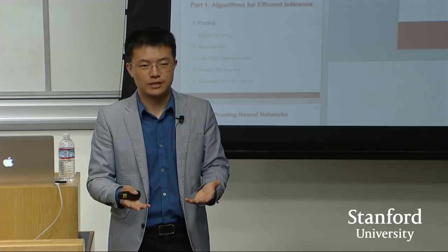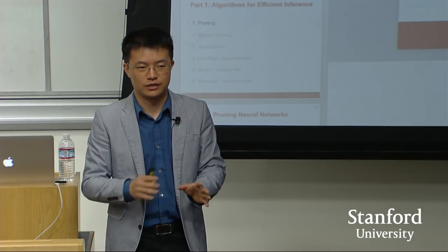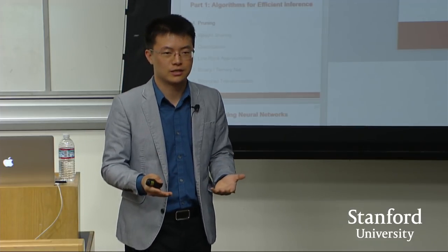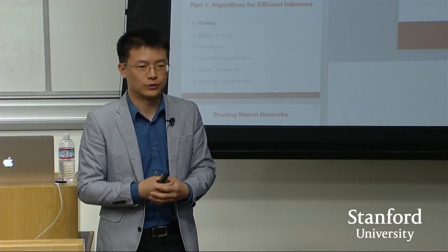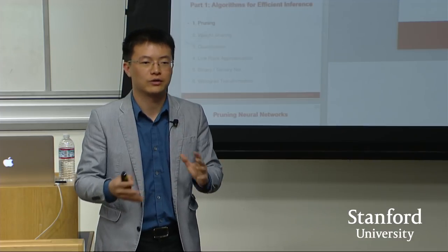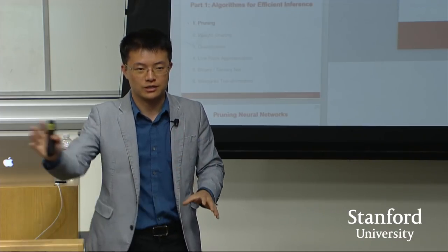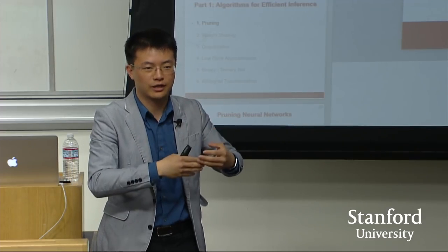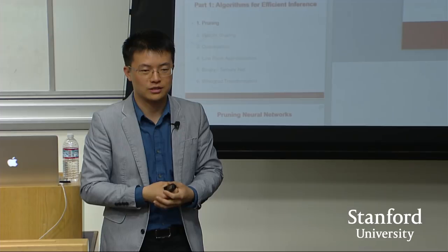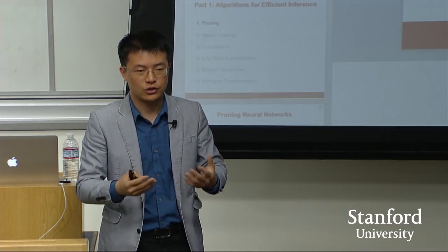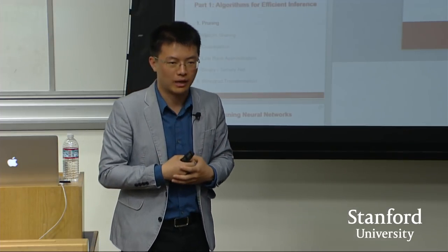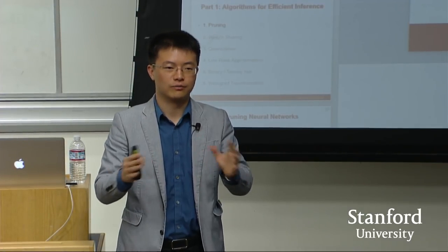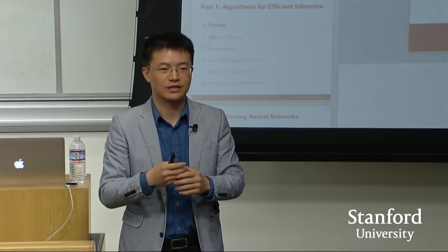And TPU basically is an ASIC, right? It's a very fixed function, but you can still program it with those coarse-grained instructions. People from Google smartly designed those coarse-grained instructions. For example, one instruction just loads a matrix, stores a matrix, does convolutions, does matrix multiplications. And they have a software-managed memory, also called a scratchpad. It's different from cache, where hardware determines what to evict from the cache.